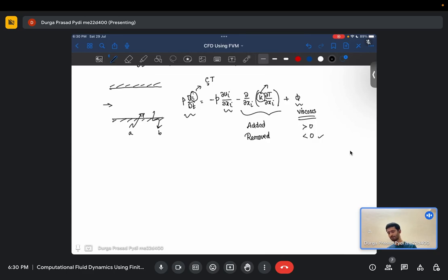The one I was trying to emphasize is this: if you just consider flow between two parallel plates, it might be a parabola, just assume it to be a parabola. Essentially each layer, when moving across another layer, will lose energy, right? If my fluid element is considered at this scale, then internally there will be a lot of these viscous forces and velocity gradients. Because of the velocity gradients, the energy will be lost and converted into thermal energy. If you are aware of turbulence modeling, you might be aware of energy cascading. If not, okay, let us forget that.